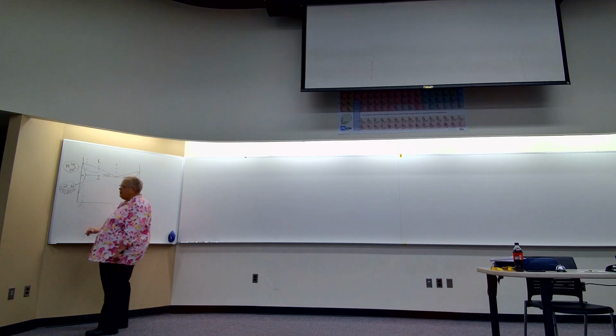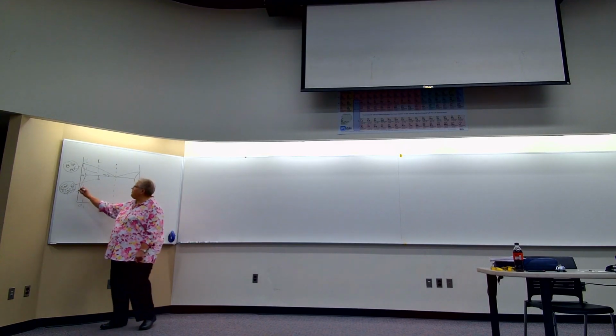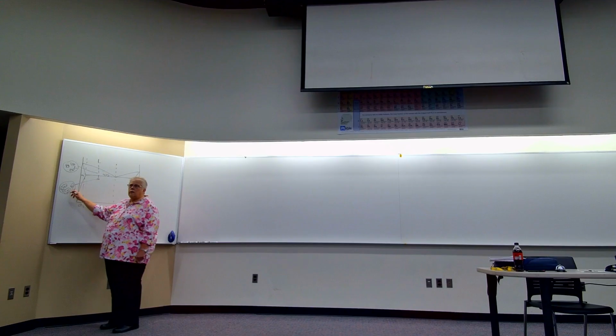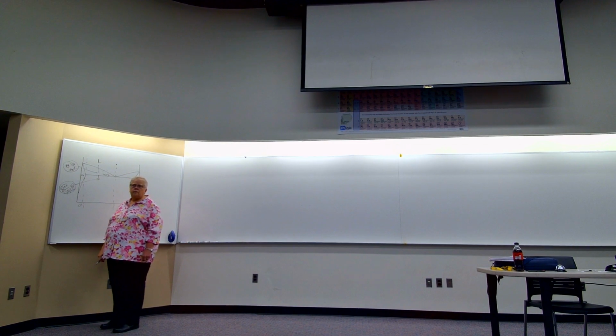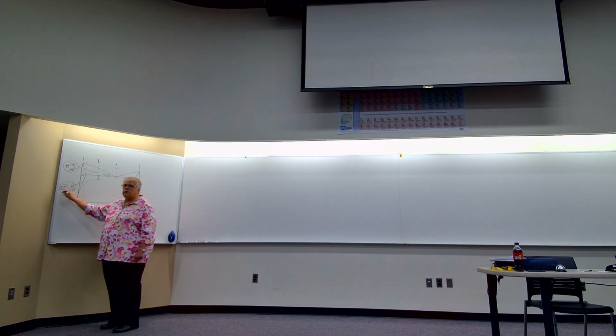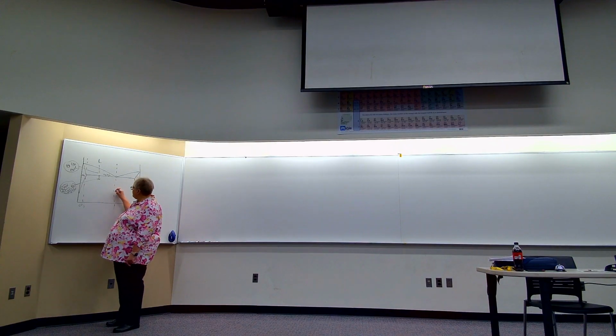So when I'm here, there's kind of two different alphas. They're the same composition, but they're in different parts of the microstructure. There's the alpha that formed pro, ahead of the eutectic, these big areas. And there's the alpha that formed in the eutectic. So when I say, where's the pro-eutectic alpha, or the pro-eutectic phase? That's this, the rest would be eutectic. Okay? This isn't on your homework, but as I go, at this composition, I have 100% eutectic, yes?